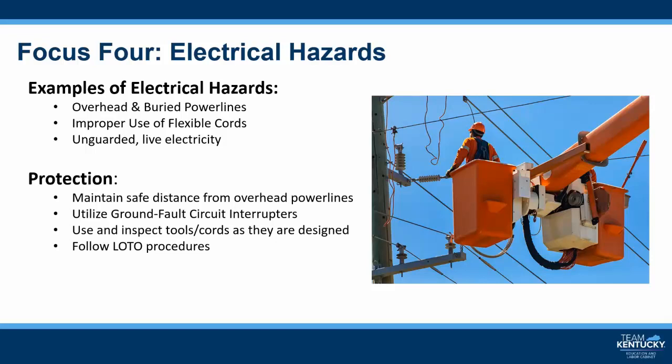The normal wear and tear on extension and flexible cords can loosen or expose wires, creating a hazardous condition. Cords that are not 3-wire type, not designed for hard usage, or that have been modified increase the risk of contacting electrical current. With the wide use of power tools on construction sites, flexible extension cords are often necessary. Because they are exposed, flexible, and unsecured, they're more susceptible to damage than fixed wiring.